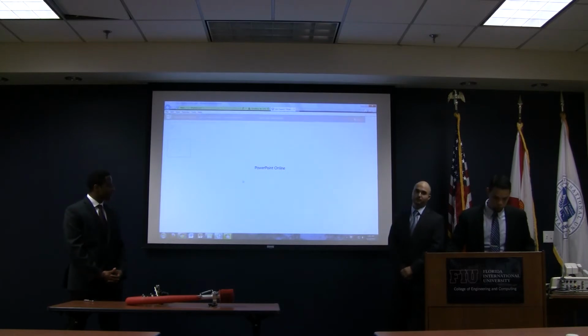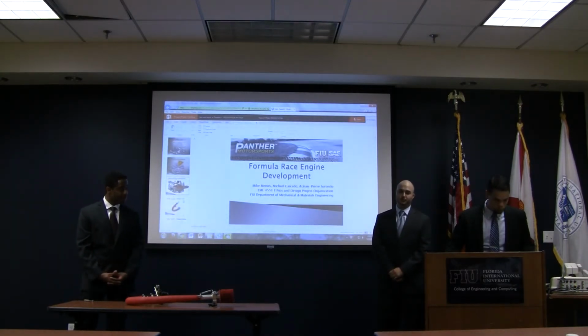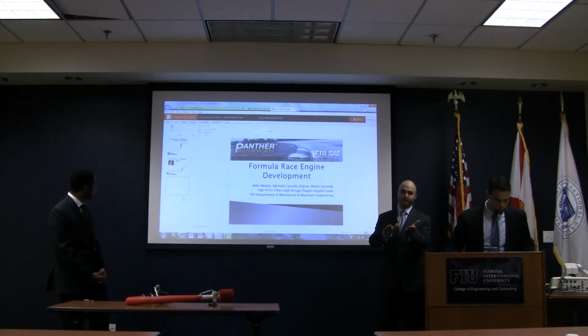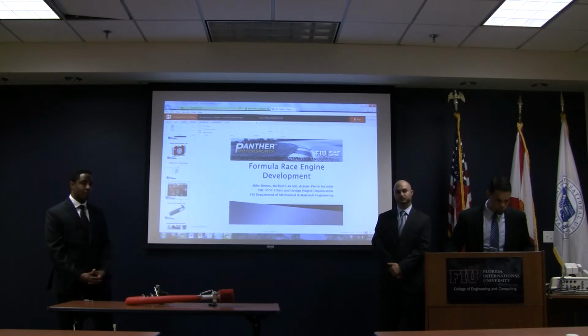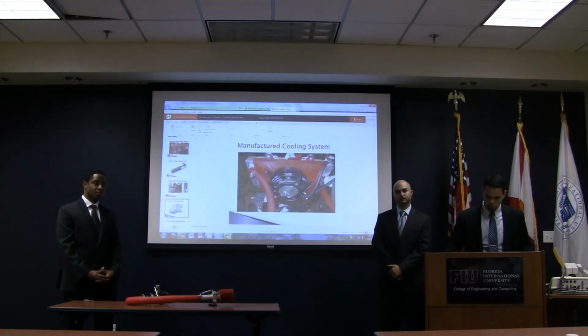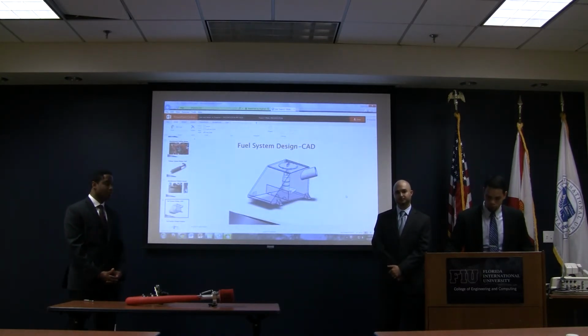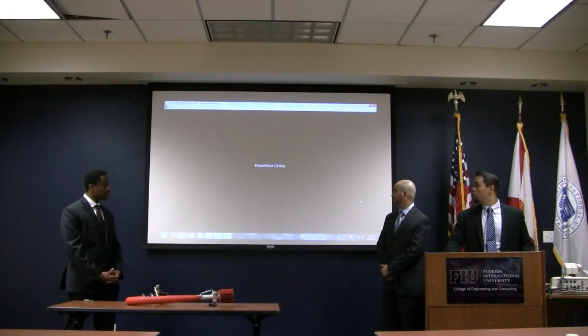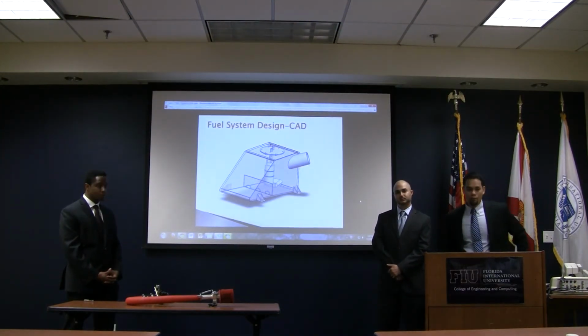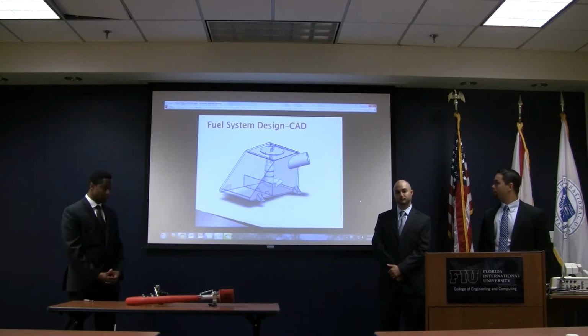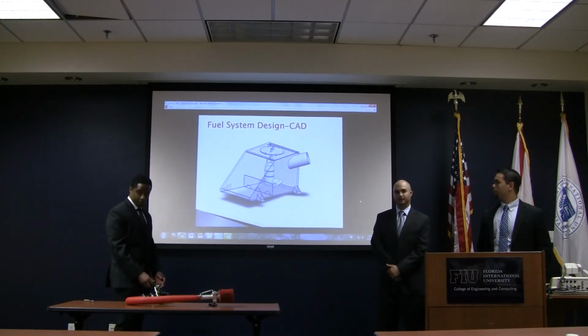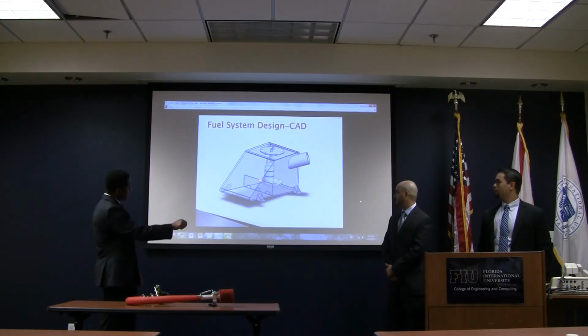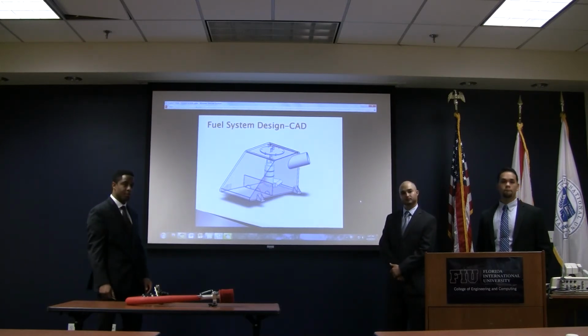So it does have a baffle to prevent the fuel sloshing. Also, the tank is sloped upward to match the upward slope of the chassis. Right. So all the fuel will tend to want to go towards the rear. Okay, and I understand you incorporated it with the seat and all that, because that's difficult. The baffle is that little bar in the bottom? Yes. It's got three 1-inch diameter notches for the fuel flow. That kind of did catch my attention.